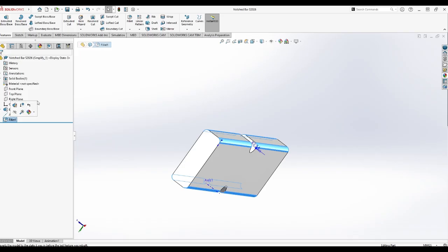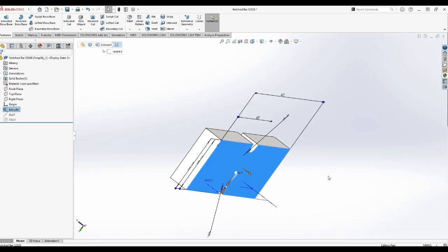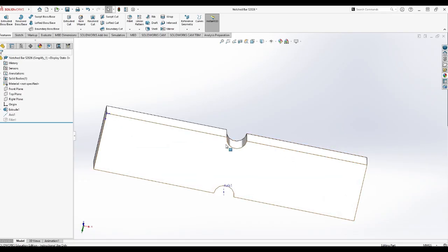Now you can see the part has straight edges. This will make the meshing of our part easier. Keep this in mind: the notch feature is not something that we can simplify. Why? Because it will affect our results. It will affect the values of the stresses and the strain, and therefore the strength of the part. So this is not something that we want to simplify, and we will keep this feature. We have to be careful about what we are simplifying and what we are not simplifying.